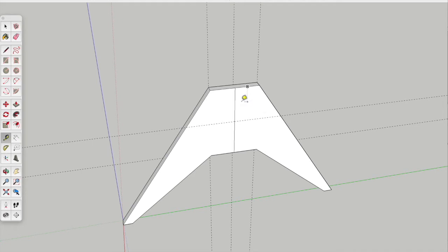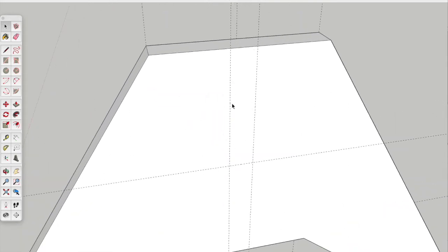So, here we go. Since I want the slot to be 15 thick, I'm going to make that 7.5, because that line is at the midpoint. Make it 7.5 that side. Now I can delete my line, and what I should have, and I can just check it, is two guidelines here that are 15 millimeters apart, and you can see that's accurately done.